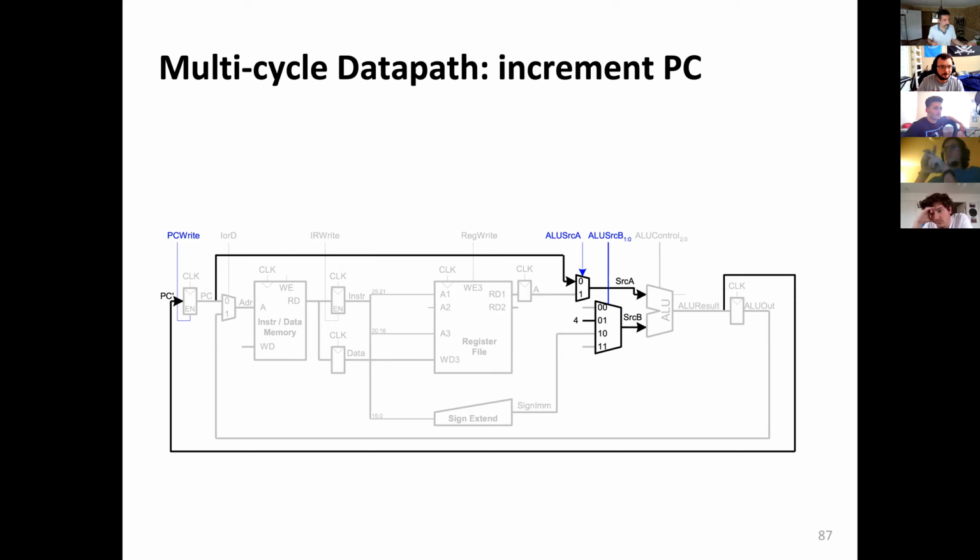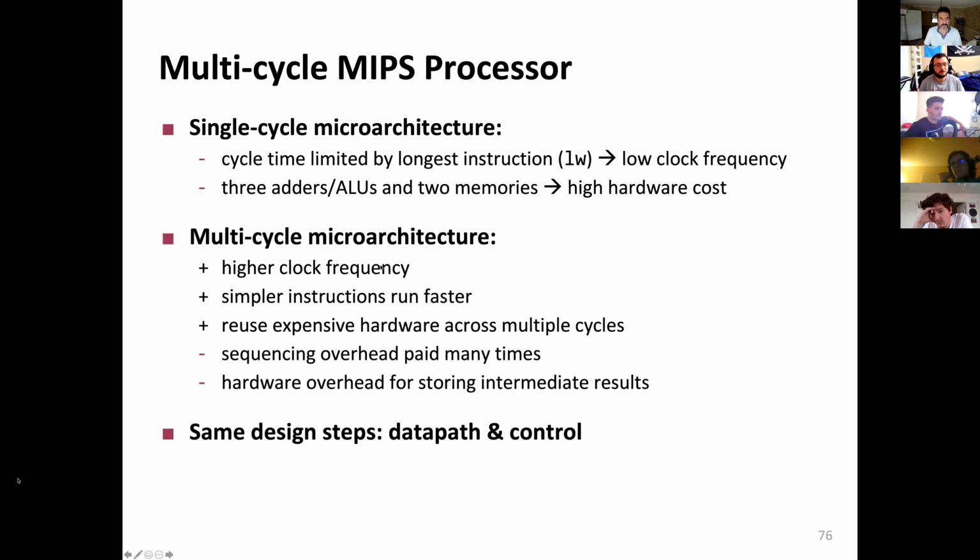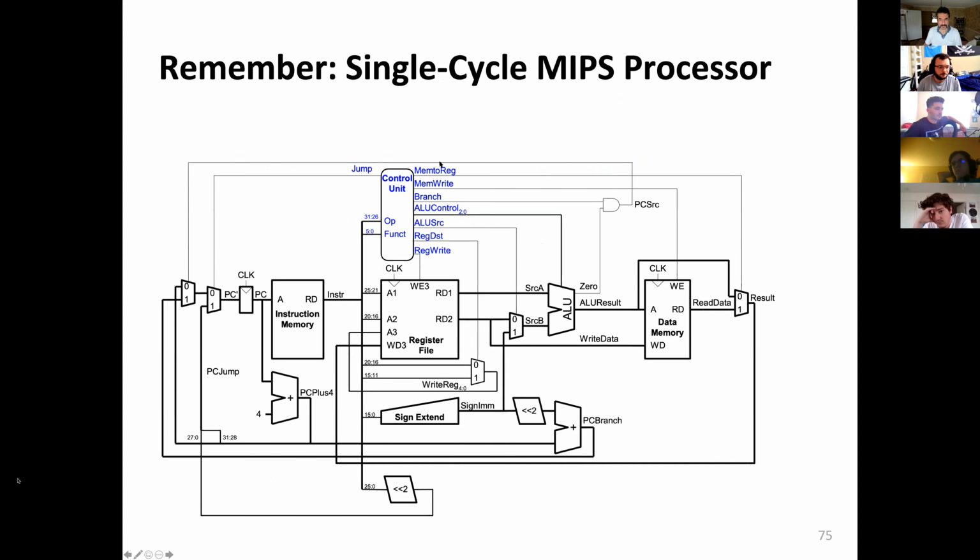It'll malfunction. Yeah, but for example, let's go back to this single cycle design. This was our single cycle, right? Couldn't we add a flip-flop here? We had a bunch of stuff; we even have an additional adder. We added some crazy nonsense hardware there. But a flip-flop is simple, right? We could randomly add one in between. What could go wrong? In this line, we cut it and we put a flip-flop. We ask it, would you please store whatever I have in instruction memory there, and then later on pass it over to the next stage.